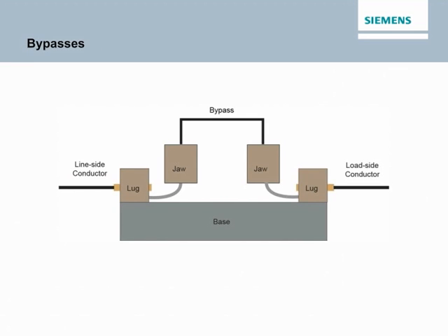Because a self-contained meter completes the circuit between the utility and the customer, in order to change the meter, the circuit must be broken. This is often not acceptable in some applications and can be a safety hazard to utility personnel. Therefore, some meter sockets have a bypass that, when engaged, provides a path for unmetered current flow when the meter is pulled out. Common types of bypasses include lever bypasses, horn bypasses, test block bypasses, and plunger bypasses. The type of bypass used depends on electric utility requirements.